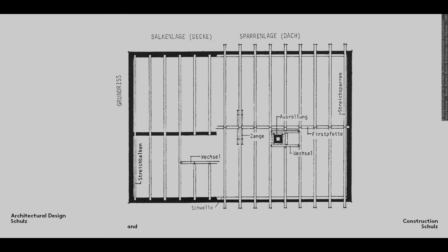This drawing shows a purlin roof with a single vertical post, that is, with a ridge purlin. The separation into two plan view planes is not immediately visible and needs to be indicated more clearly. However, it does show quite clearly the relationship between the joists and rafters and the members below them, such as the edge rafter and the trimmers around the fireplace.